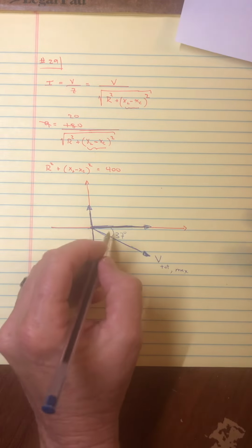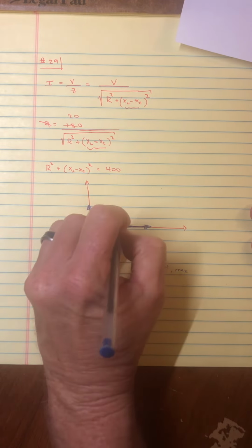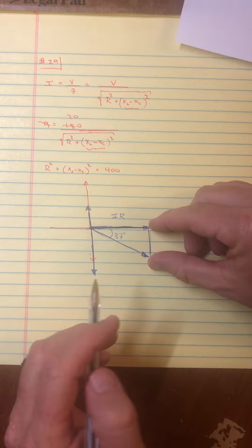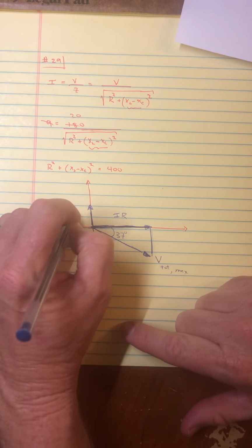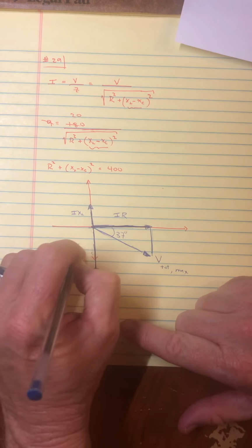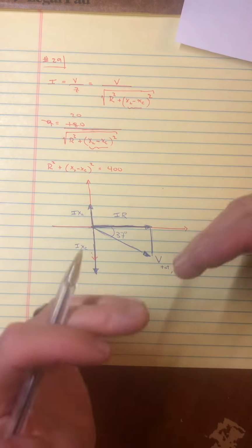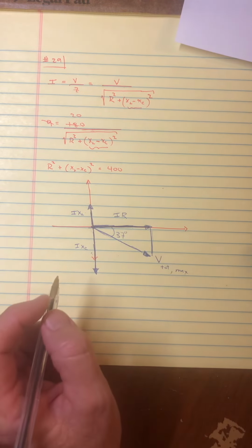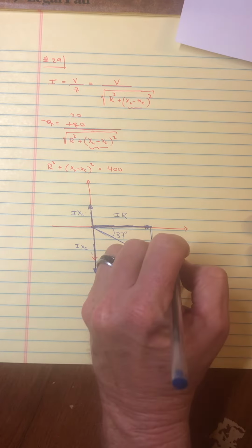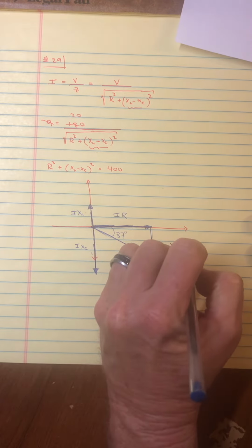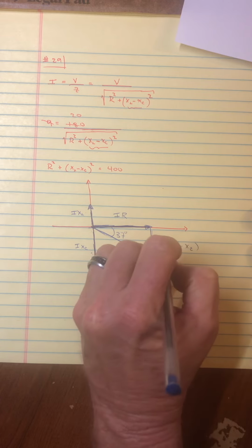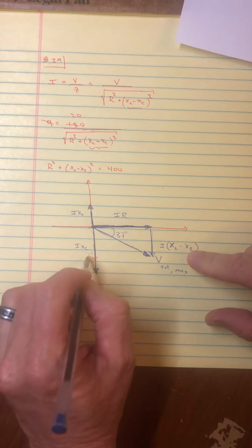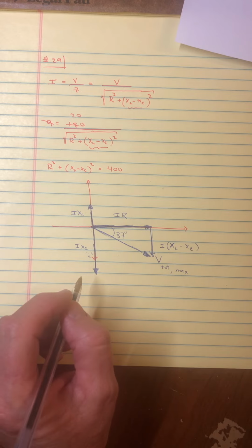All right, so what we said then is this being the voltage on the resistor would be IR, and the length of this vertical piece is actually the voltage on the inductor and the voltage on the capacitor fighting each other. And so this right here becomes, and we usually write it as XL minus XC times I, meaning it's pointing down. We would have a negative number. The voltage on the capacitor is a little bit more.